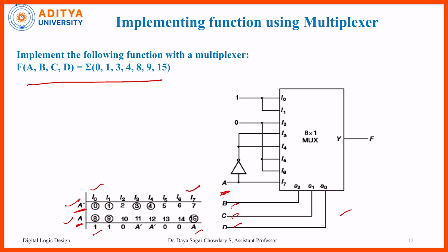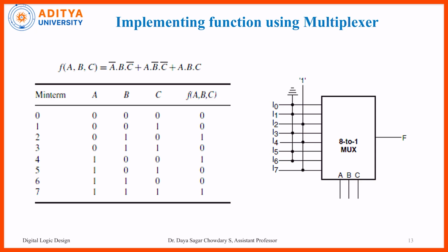Likewise, we have to start our work. And here, this is an equation given, but we have to first construct the truth table. So that is from 0 to 7 because 3 input terminals are there, that means A, B, C. So if 3 inputs are there, 2 to the power of 3, so totally 8 combinations. So for 8 combinations here, A bar, B, C bar. That means A bar is 0, B is 1 and C bar is 0. So 0, 1, 0 here.